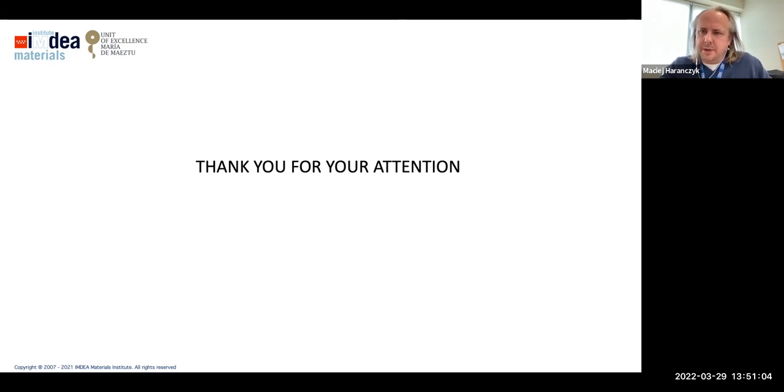It's more complicated. R square is just one metric. You should look at the mean absolute error or mean square error, because it's also an important metric. I usually like the first assessment to just visualize, just look at predicted and simulated, because it gives you very fast the idea where the error is coming from.